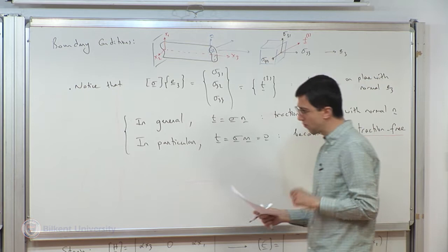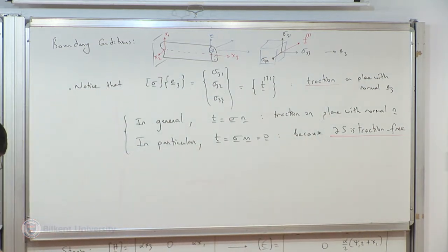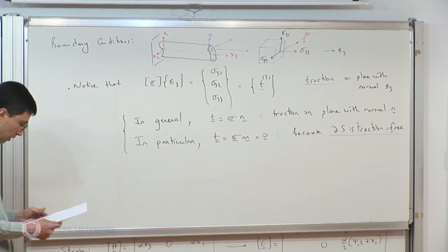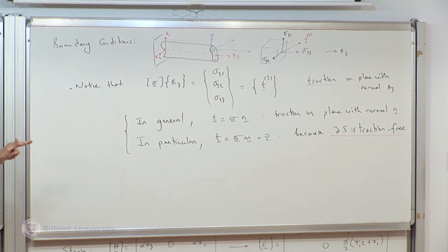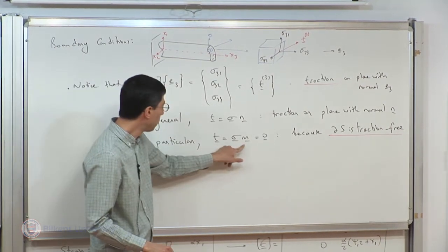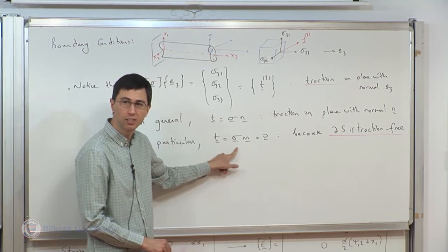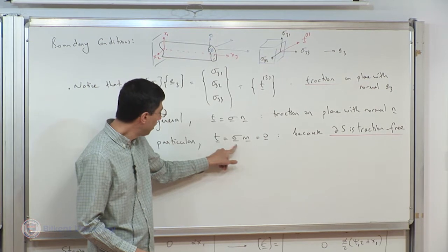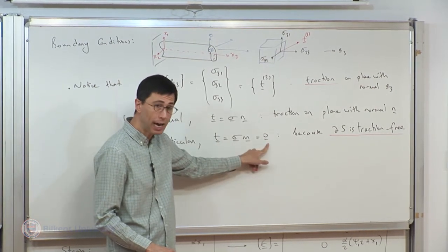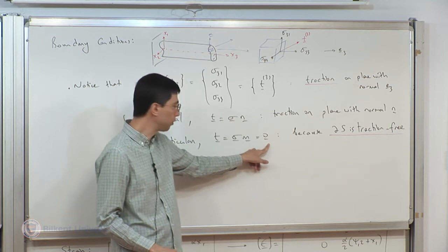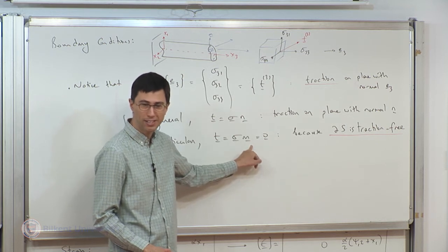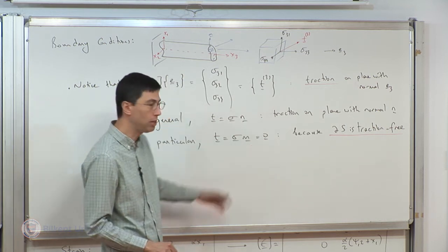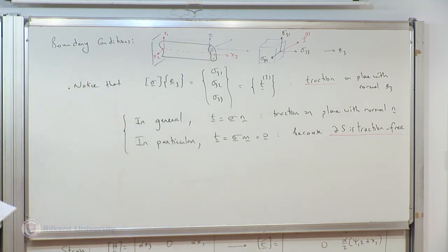So now that piece of information is essentially why we had to just quickly introduce the concept of a traction over here. Now I'd like to calculate the traction, but for that now, I know what the stress looks like. I've just calculated it before invoking equilibrium. Now to impose a traction or check whether I have traction-free boundary conditions, I need to calculate the traction, and for that I need to know the normal to the boundary. And so that's one additional piece of information that now I need to construct for an arbitrary cross-section. And I will do that, I think, over here.